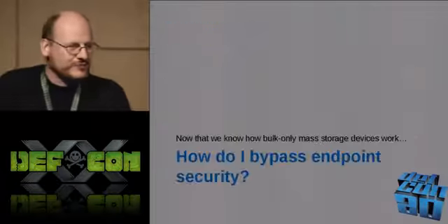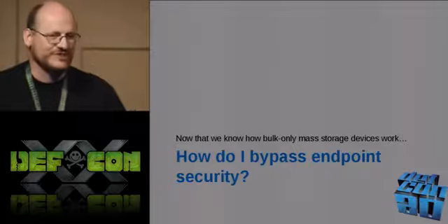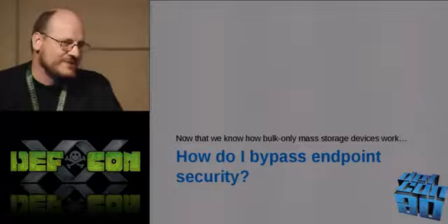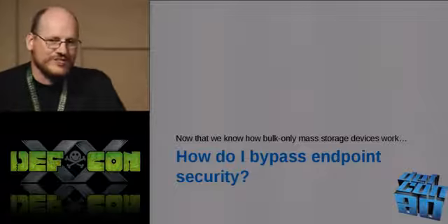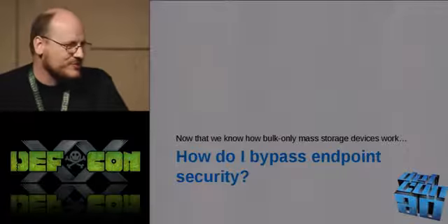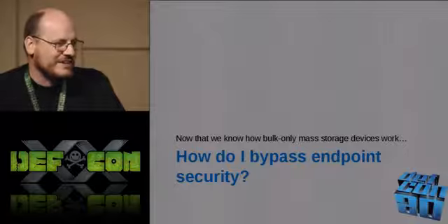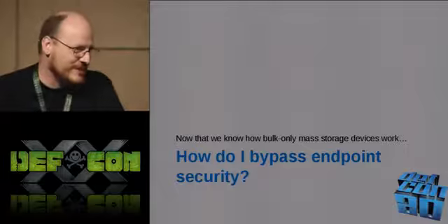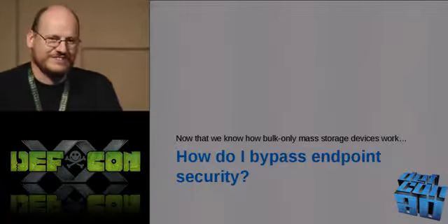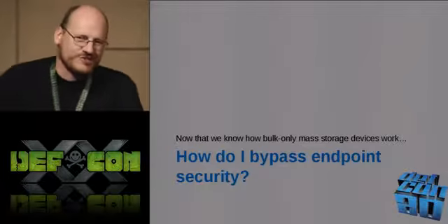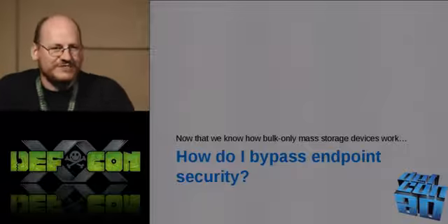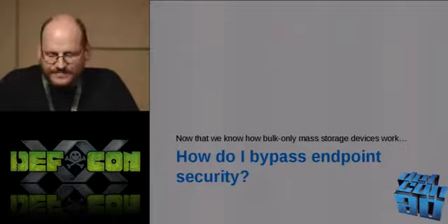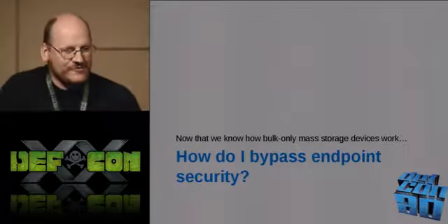By the way, if you're cheap and you want to view all this lovely USB traffic and you have a Linux machine, if you don't know this, you can use usbmon. So if you just do a modprobe usbmon and you fire up Wireshark, guess what? All of a sudden you have a bunch of USB buses available for you to trace this stuff on. Comes in handy. Of course, a hardware USB tracer would be nicer, but they're a little bit more expensive than free. So.